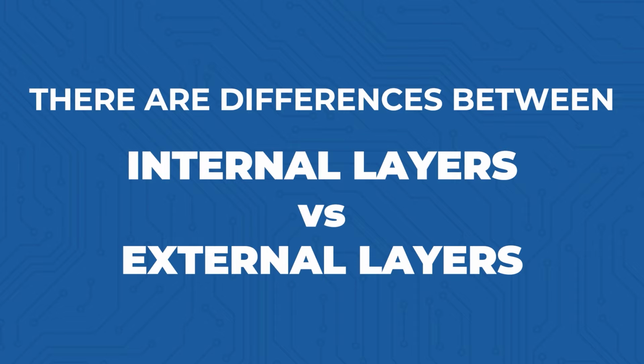Internal layers, they don't receive any airflow. The same size trace can carry less current when on an internal layer versus an external layer. Just keep that in mind.